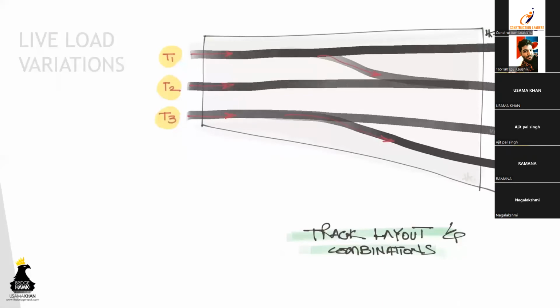This was a span which I designed for North Mumbai Metro, and this shows the number of tracks that I experienced. This is a trapezoidal span, and on it we had 3 straight spans, track 1, 2, and 3. But we've also got mergers, track 4 and 5. So you need to properly simulate and prepare as load cases all the different track conditions that could possibly be experienced by the span in its serviceable life.